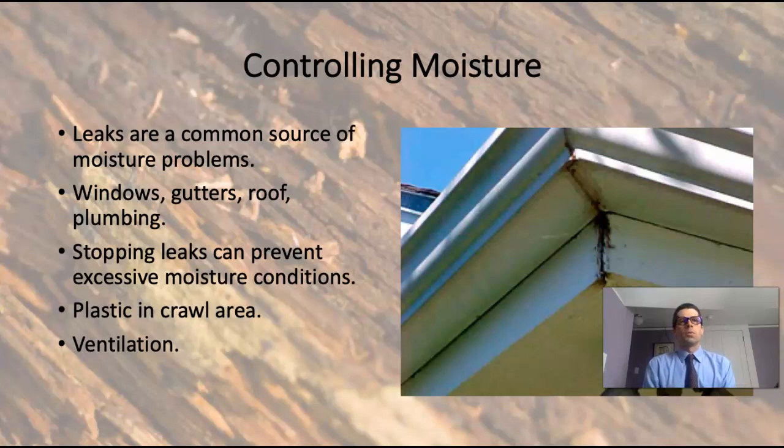We're going to roll out 6 or 8 mil polyethylene, I think it is, plastic, and we're going to roll that underneath the house, and we're going to get those big landscaping staples and staple that down so it doesn't just blow away as soon as the wind blows. That's going to prevent a lot of moisture that's creeping up from the ground from getting absorbed by all of the framing materials underneath our house.